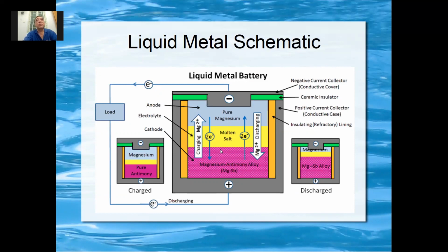So it's not suitable in a place where it will rock. Even if you put it in a bus, the bus is not likely to rock so much. But what if the bus overturns? Then the battery, you'll get into trouble. As long as it moves, it starts to rock, then it's not advisable. Right? So normally these are put stationary on the floor.